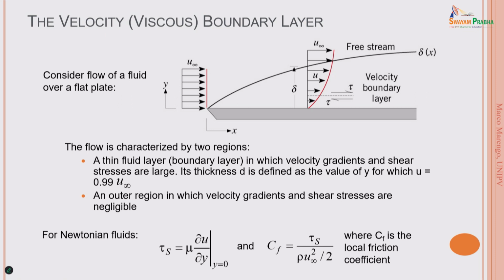The viscous boundary layer is defined as the position in space, let's say, normal to a surface. The surface can be in any position. We go normal to the surface, and we capture the point where the velocity is 99% of the undisturbed velocity, the one that came from a direction, and the velocity was changed because in contact with the wall, the velocity becomes 0.